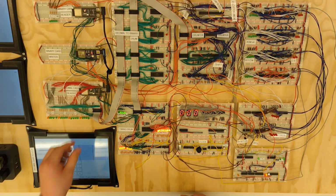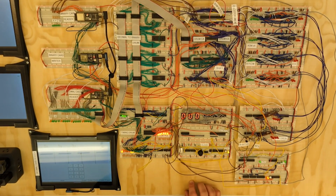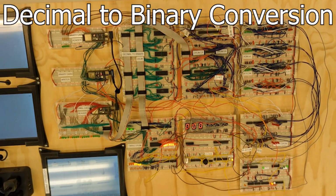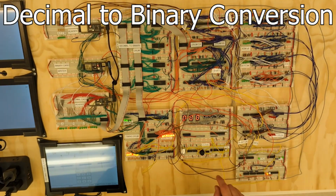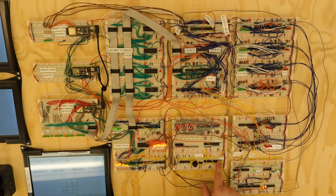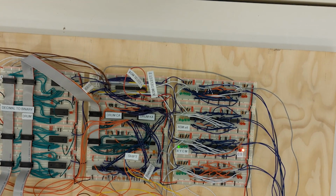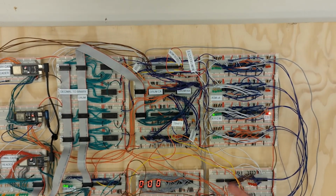With these drums now reset, we're going to go ahead and enable the ESP module, and again step through the decade cycles until we reach 1 again. Now we can verify that we have that data loaded in by just stepping through some clock cycles. We should see that at address 0, we have 1 bit lit up on both the second and third columns. Then at address 1, we have only 1 bit loaded on the third column because this one is storing the 1 and this one is storing the 3.